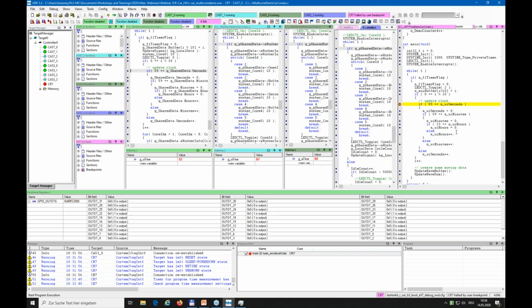If you want to put back the Cortex-R core to the run control group, then you have to stop all the cores. It is only possible to change the run control group settings if all cores are stopped.